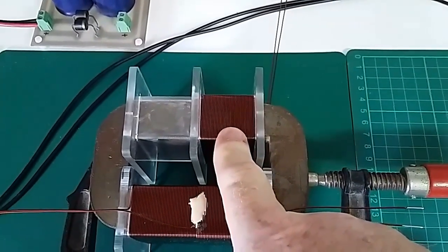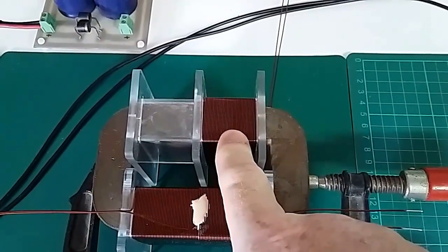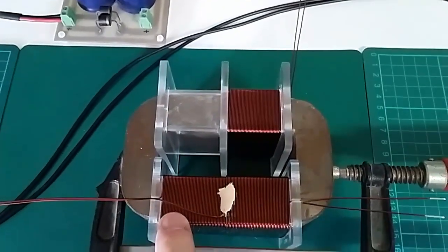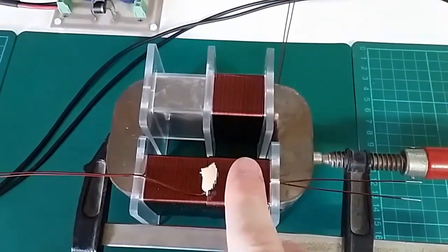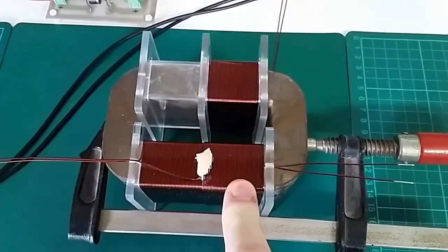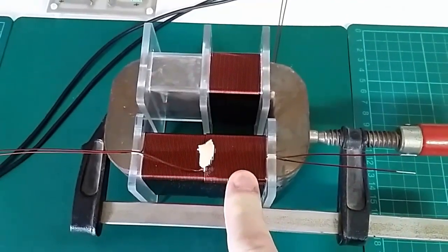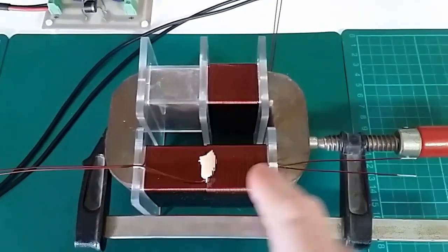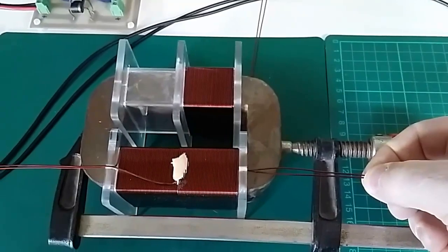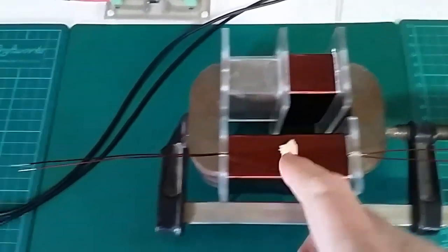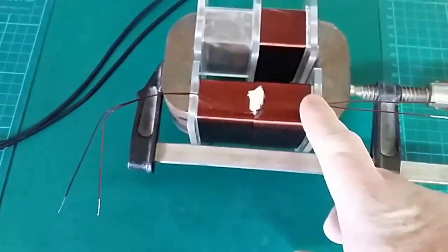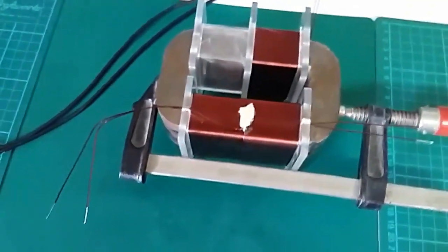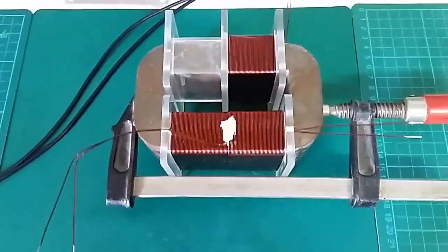I think the inductance is fairly close, 412 compared to this coil over here being 394 I believe, off the top of my head. This coil here, I think, was about 94 millihenries, and when they are connected here non-inductively out to these terminals, I believe it was much less, something like about 13 millihenries.